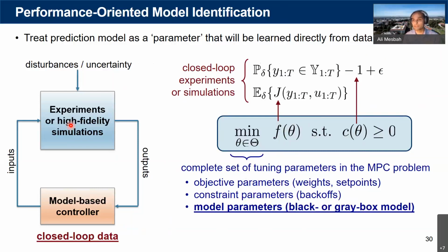Why? Because high fidelity simulations are expensive. Alternatively, what you can do, you can learn control-oriented models from high fidelity simulation and high fidelity models in a data-driven manner and use these reduced order control-oriented models for designing controllers and optimization and whatnot, right?